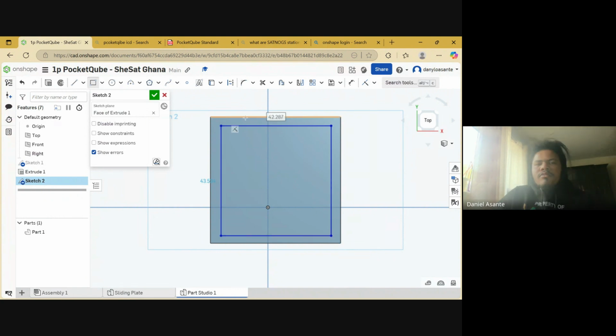Yeah, so from this box, I'm going to cut through it. I'm going to cut all this space over here so we can have a hole inside. So usually for satellite structures small like this, 2 millimeters has been proven to be strong enough in terms of structural integrity. So we are going to make the thickness of each of these walls 2 millimeters.